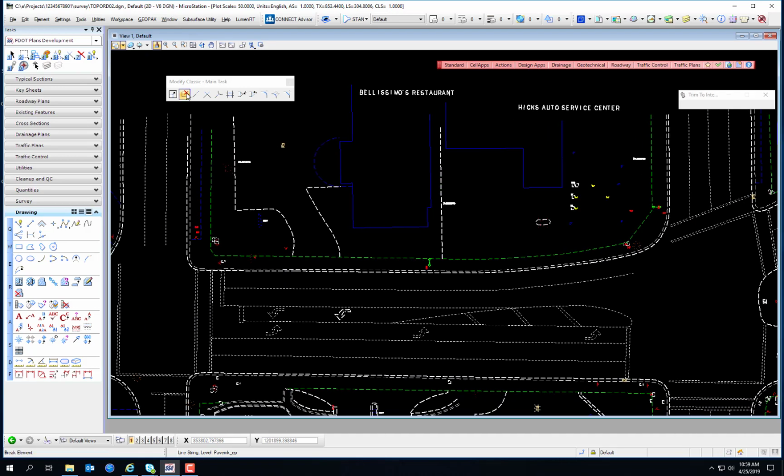Okay, Partial Delete. Let's use the Partial Delete or Break Element tool. Set it for Break by 2 points. Select the point of a building you want to break. There you go. Because maybe that building isn't quite shaped like that. What about this other building? And of course, once you do that, the building is gone. You can't re-extend it back out. It does not maintain that information.